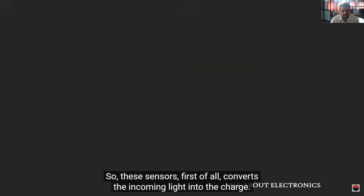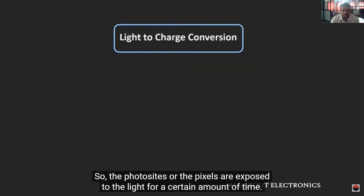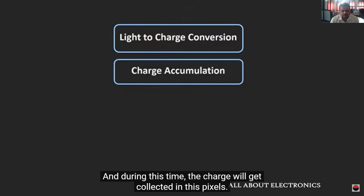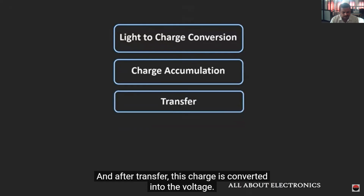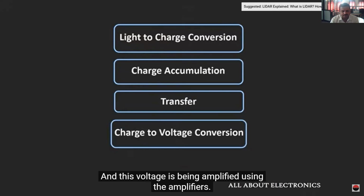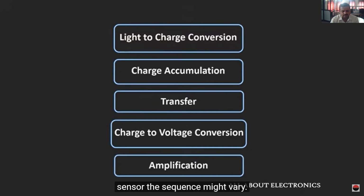The sensor first of all converts the incoming light into charge. The photosites or the pixels are exposed to the light for a certain amount of time, and during this time, the charge gets collected in these pixels. Once the charge is collected by the pixel, this charge is transferred for further processing. After transfer, this charge is converted into voltage, and this voltage is amplified using amplifiers. These are the common steps which you see in both the sensors, but depending upon the sensor, the sequence might vary.